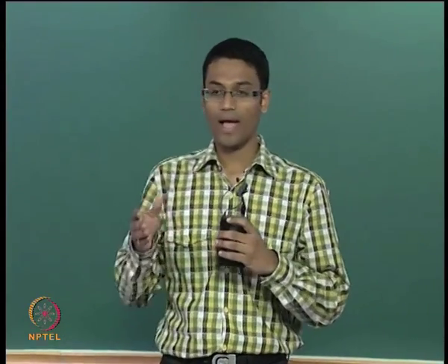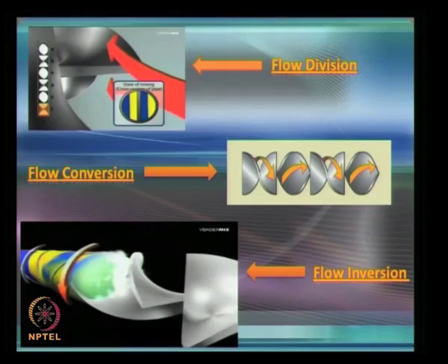Next is the mechanism. The static mixer element divides a fluid flow into two parts, and because of the helical structure of the mixer element, the fluid converges as it passes through the mixer. These processes create turbulence inside the mixer, and as a result, the fluid gets homogeneously mixed.